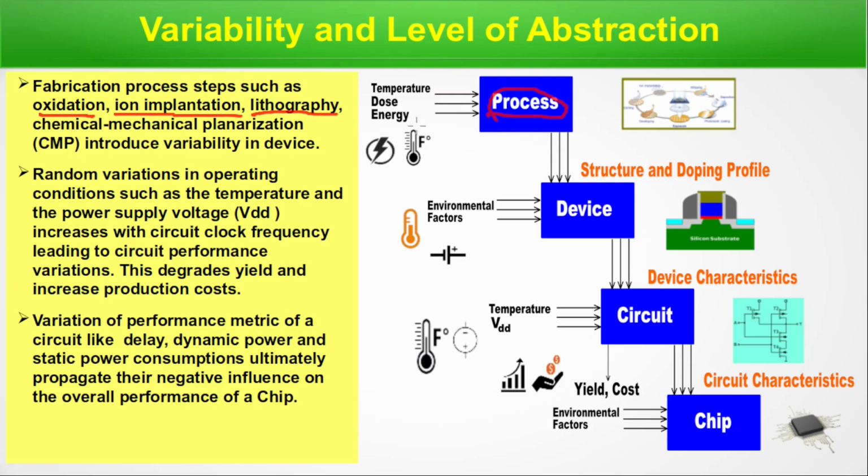are processed, especially ion implantation for those n wafers has been done with some dose and energy specification, and for the next batch of n wafers, this ion implantation has been done with dose or energy slightly different from the previous run. So with this ion implantation, how much these ions penetrate and where it would have the highest concentration, how many ions will be implanted, that might get changed because of this change, because these ions are activated with energy.